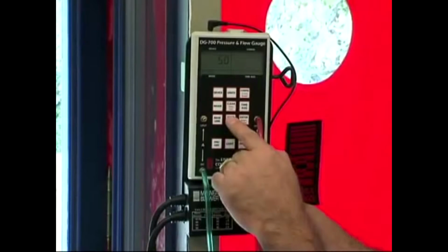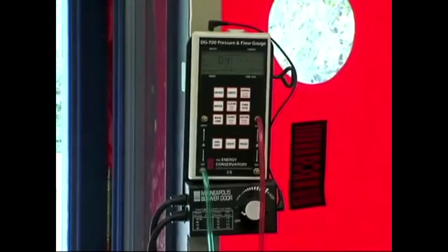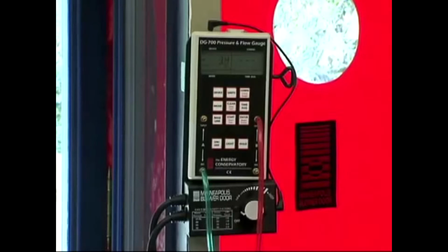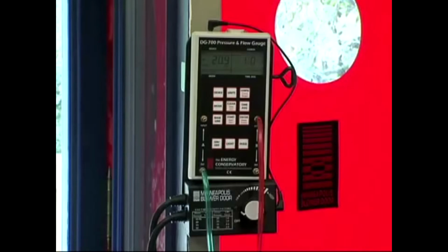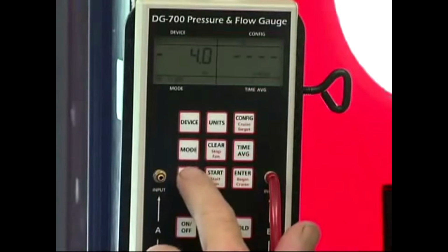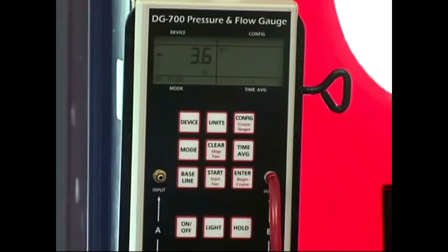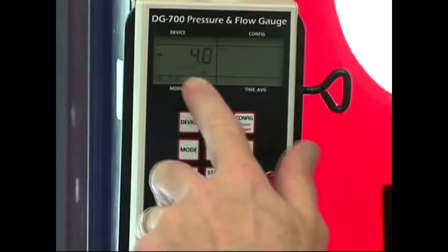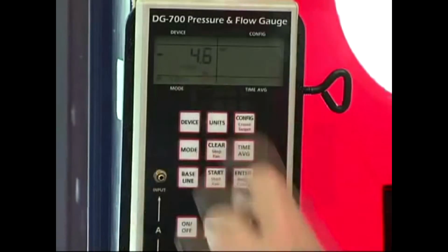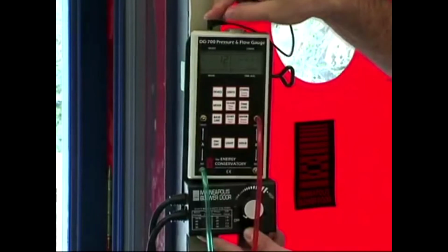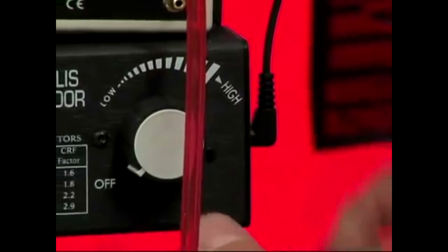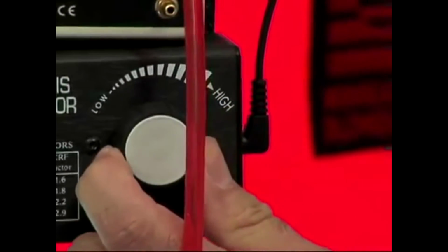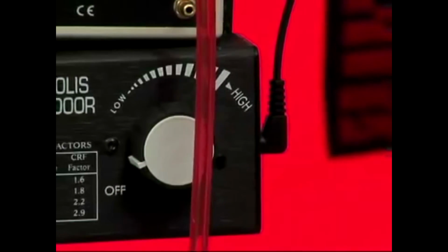Cruise control uses the DG700's fan control feature to continuously adjust the blower door fan to maintain a constant cruise target pressure on channel A of the gauge. Before starting cruise, the blower door and DG700 should be completely set up. If you wish to cruise with a baseline pressure adjustment applied to channel A, simply use the baseline feature first before beginning cruise. You will also need to install the fan control cable and turn the blower door speed control knob to the just on position where the controller is on but the blower door fan is not turning in order to allow the DG700 to control fan speed.